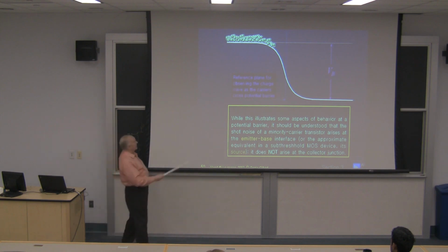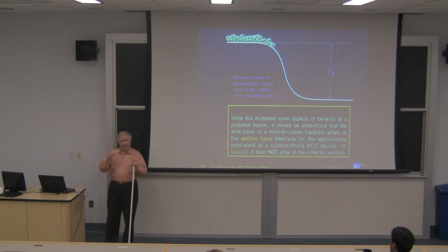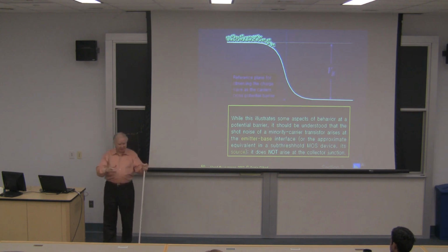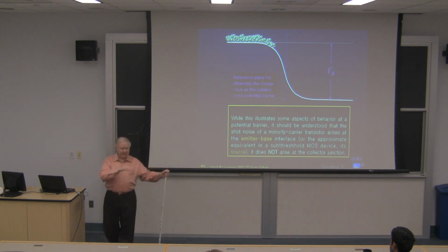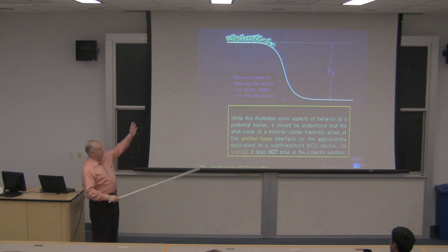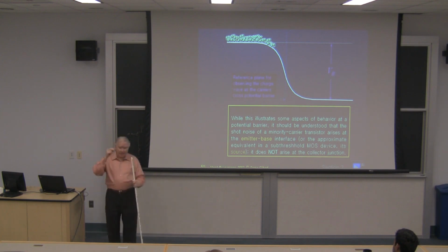In fact, these electrons have different energies because they made it across the emitter boundary due to the injection process, which isn't included in this picture, it will be in a later picture. And there is, again, the ideal gas analog for understanding the behavior of a semiconductor. It lacks in a number of ways because we forget that it's all statistical and we think of the band gap as being an absolute voltage. In fact, the band gap energy has a distribution. It comes out of the density of states. There's an energy distribution of those carriers, and some of them will make it across the boundary and some won't, but to the degree that the highest energy electrons make it in there, they carry that energy with them across the base, and they appear at random times in the collector, but it's actually the emitter.